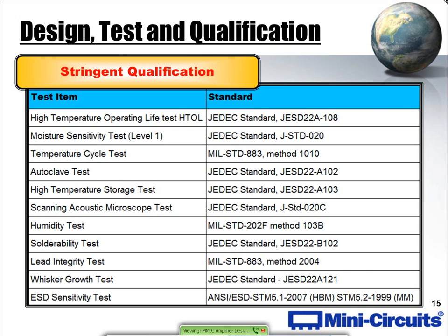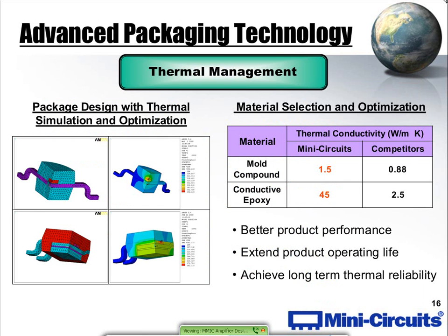The other areas of multidisciplinary design are in the packaging. This is typically not done by your circuit designer, but you'll have a package design team. And these engineers are making use of a wide variety of materials, whether they're plastics or ceramics or epoxies, designing the lead frames, and they're really focused on a few things. They're focused on protecting the device and getting the heat out and getting the lowest parasitic package to have the least degradation on the performance of the chip.